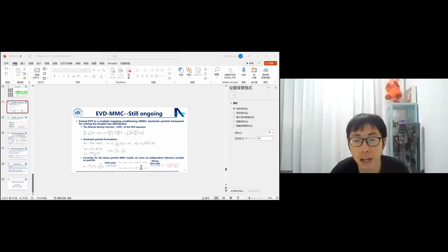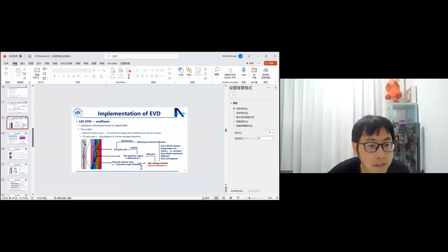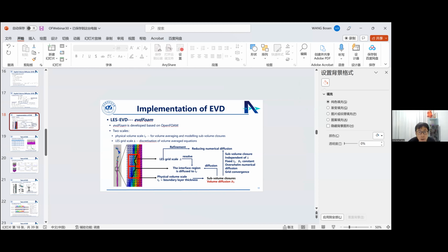Yeah, and I can give you the value. After our tests, we found the numerical convergence usually reaches about 4 to 5 volume cells. That means the characteristic grid size near the interface is about 1/4 or 1/5 of the boundary layer thickness near the interface for our method. Yeah, this is the answer. I'm not sure whether I answered the question or not. Okay, thank you very much.